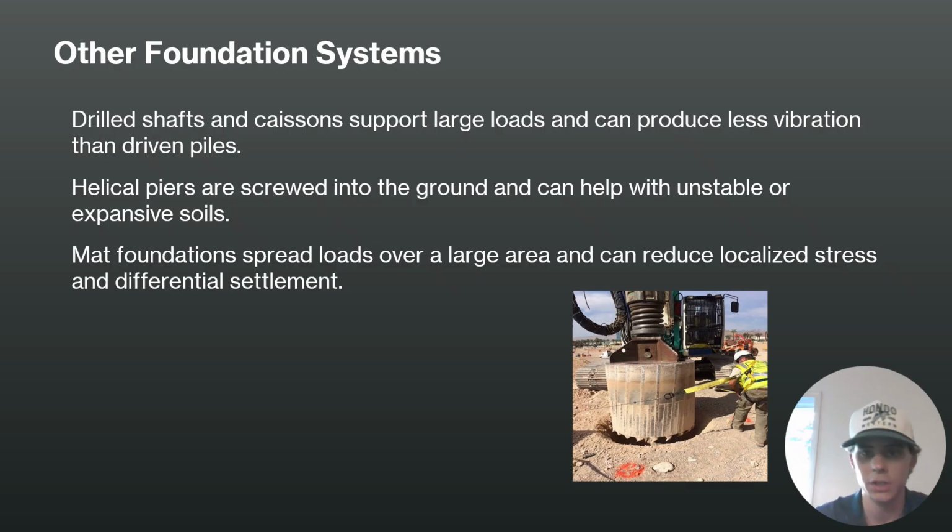Mat foundations work a little bit differently. Instead of going deep, a mat foundation focuses on spreading the load across a large surface area. This can reduce stress on weaker soil and help reduce differential settlement.